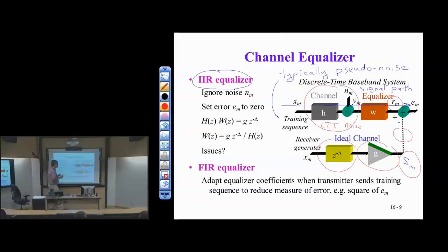Correct. So the input's the same in both cases. In the signal path, it's the actual transmitter that transmits this training sequence. In practice, it'll be pulse-shaped and all that. But here I'm just showing you, for the purpose of the homework and for these slides, X of m is just symbol amplitudes coming at us. Or it could be samples, I suppose, PN samples, since m is the sampling rate. So this is just samples coming at us at the sampling rate, not the symbol rate.